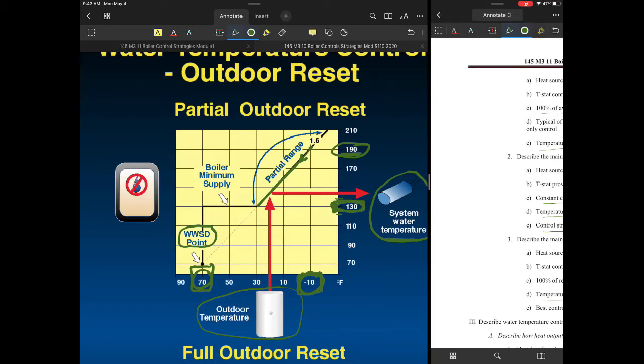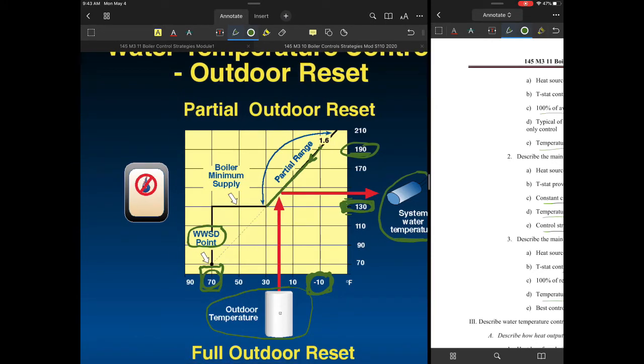So you might determine that, you know what, I'm going to set 140 or 135 or 125. You have to figure that out. 130 is actually, I think, a pretty safe number, 130 to 140. I've had commercial boiler systems guys come out, when I'm doing control work on a commercial job, and those guys would specifically say, I don't want any less than 140. I think that might be pushing it a little bit, but that's what they wanted. So as long as that boiler was under warranty, we had to pretty much set the lowest temp we would allow to that 140 degrees in that case.